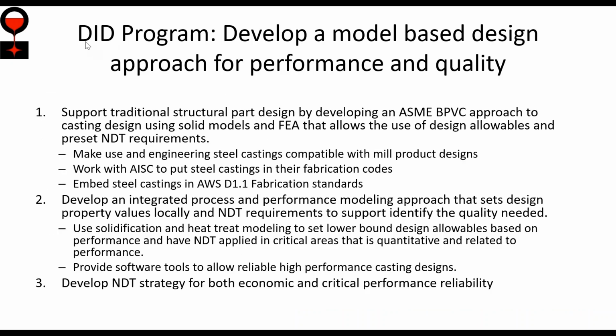This is what I was talking about before. Our digital innovative design program, we're actually trying to develop a set of standard NDT requirements. So just like in the boiler code, a common fabrication person can pick out a 3D geometry they want made as a casting, and then we want to embed the NDT and the allowable properties into the AWS D1.1 standard and into the ASTM standards, so that this is seamless to use castings with all the other steel mill products